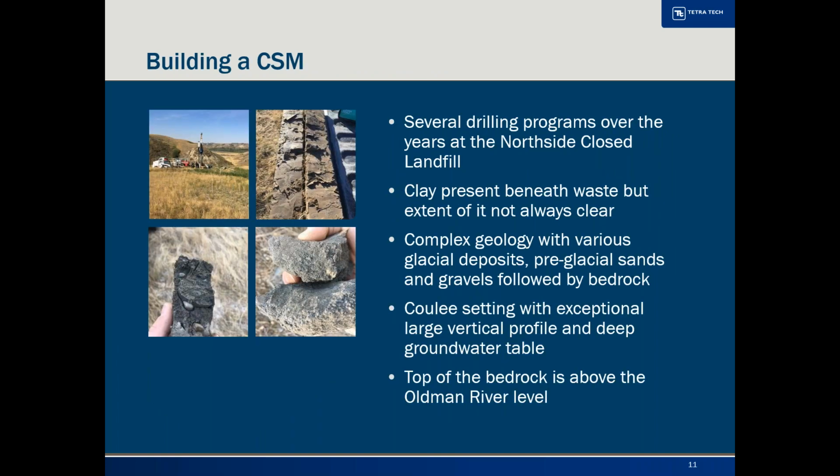Thank you, Mandy. Yeah, so the Northside closed landfill, what we have been doing over the years is monitoring and slowly building a conceptual site model, which is basically a description of how the site behaves, what the impacts are, what the pathways are, and whatnot. So we did it over the course of years with several drilling programs. Most recently, actually this spring, we installed a couple of more wells to assess the groundwater and groundwater quality and identify the stratigraphy further.